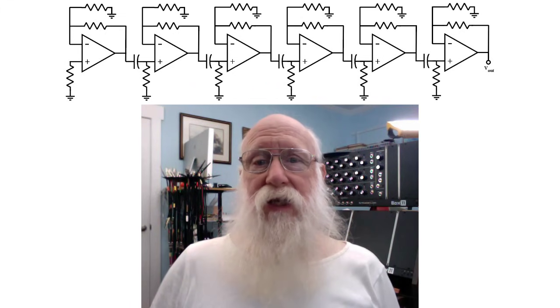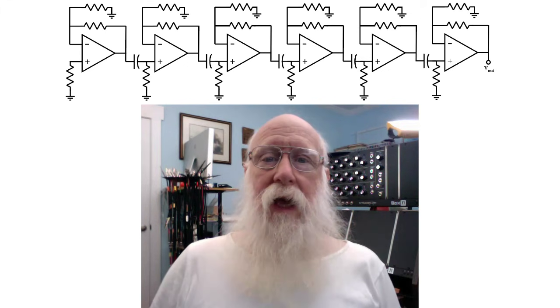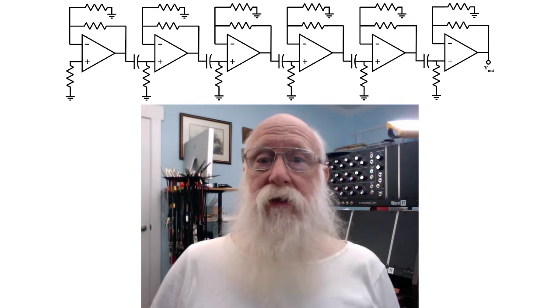In order to construct a noise generator with a several volt output, we have to have some original noise to work with. There are several places you can obtain a basic noise signal. I've seen suggestions that you can obtain it from a DC motor, although that has the problem that it doesn't have a flat frequency distribution. I have seen a suggestion that you could simply cascade several operational amplifiers in series with no input to the first one and with fairly high gain on all the stages to just amplify the noise that the op amps